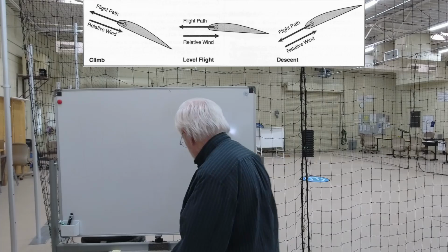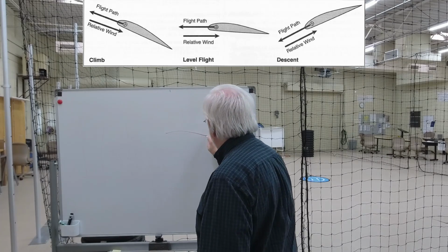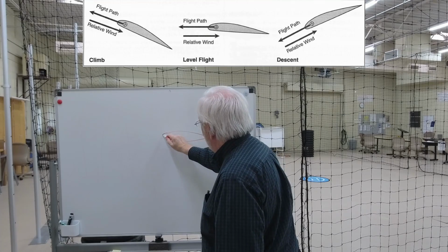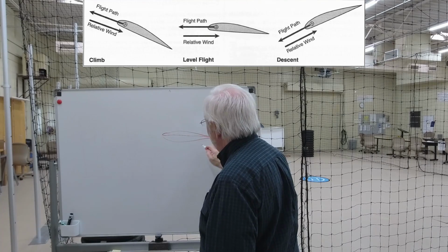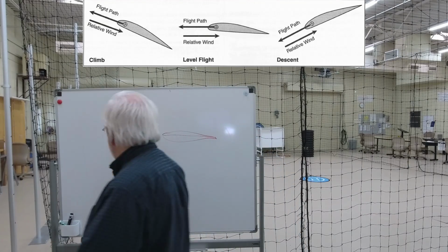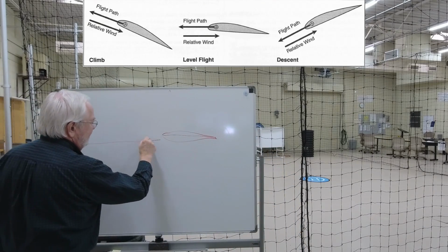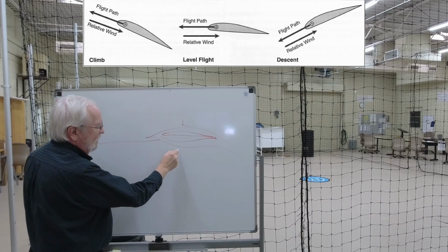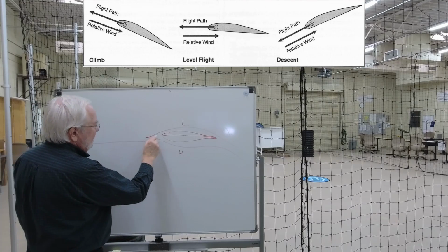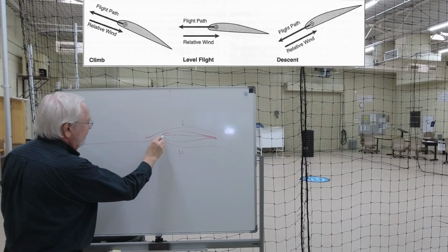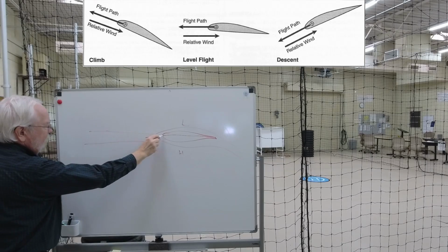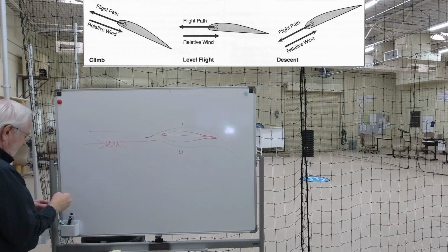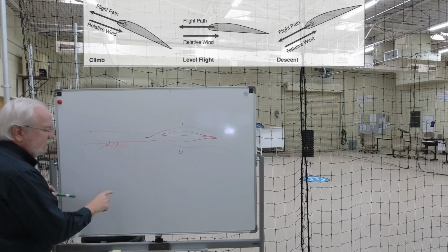It's just simply the term angle of attack is defined as the angle between the wing chord line and the relative wind. For example, my crude picture of a wing: it is the chord line, which is that line that goes from the leading edge to the rear edge. Relative wind is simply the wind as it's blowing across the airfoil, right? Remember those diagrams where the wind goes around it, low pressure on the top, high pressure on the bottom, basically, right? It's this angle between the extended line out from the wing chord line and the wind. That's all that is, okay?